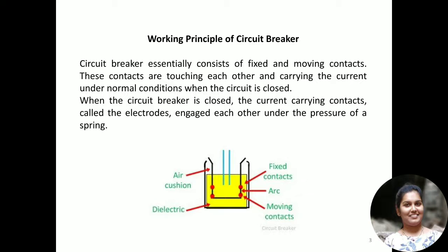There is an arrangement of potential energy stored in the operating mechanism of the circuit breaker, which is released if the switching signal is given to the breaker. The potential energy can be stored in the circuit breaker in different ways, like by deforming a metal spring, by compressed air, or by hydraulic pressure. But whatever the source of potential energy, it must be released during the operation. The release of potential energy makes the moving contact slide in a speedy manner.